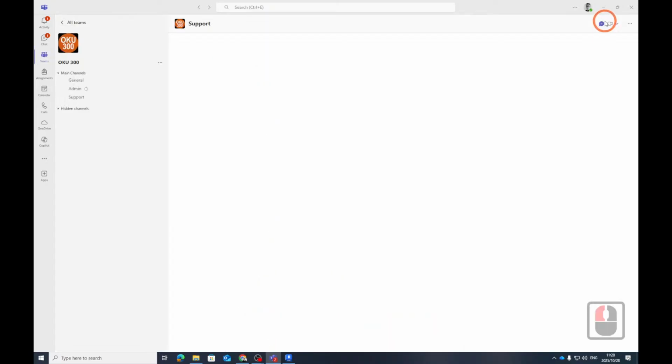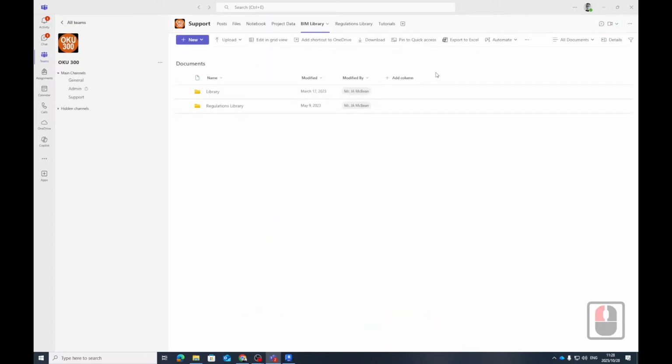Okay. And where does the water connect to? Then you're going to have a sewer, because as this, you're going to have a big main sewer, and this is your existing sewer, and that's usually a dark, thick line, and you call this existing sewer. Now, typically this will connect to existing sewer, and there's usually a manhole. Go and look on the sidewalks. There's a manhole where it connects.